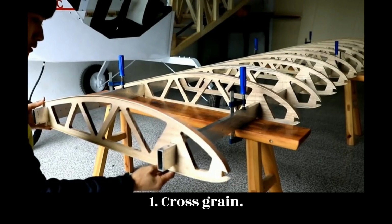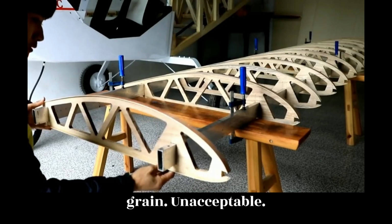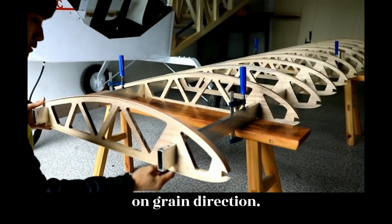1. Cross grain. Unacceptable. 2. Wavy, curly, and interlocked grain. Unacceptable. 3. Hard knots. Unacceptable. 4. Pin knot clusters. Unacceptable if they produce large effect on grain direction.